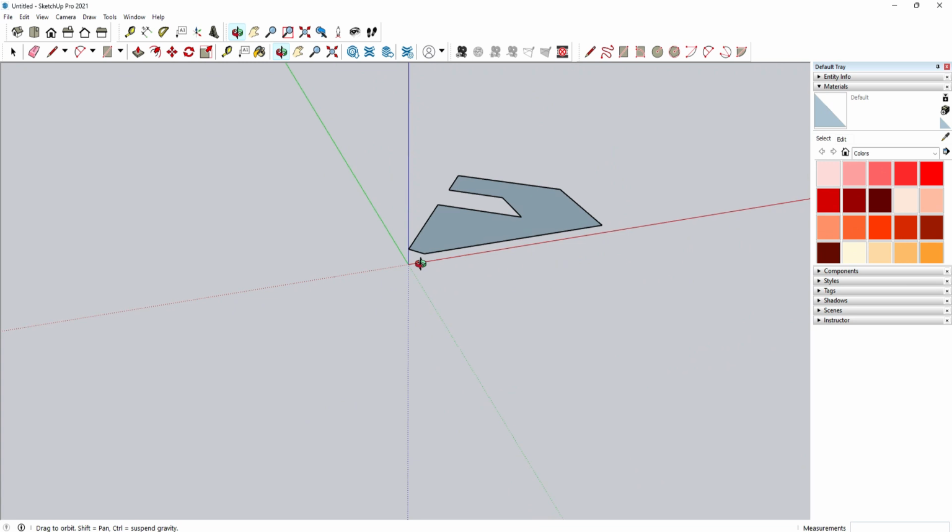To draw a rectangular vertical face, hover over the desired corner point and move down, in blue, and click when the double constraint appears.